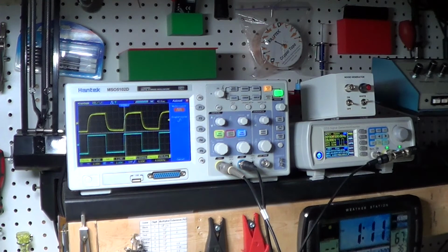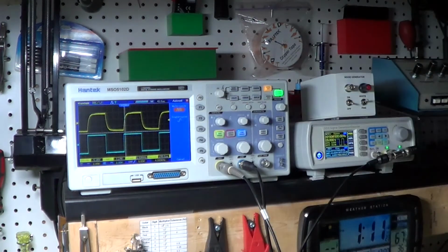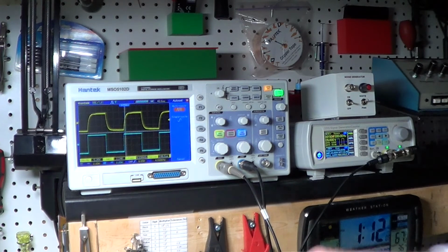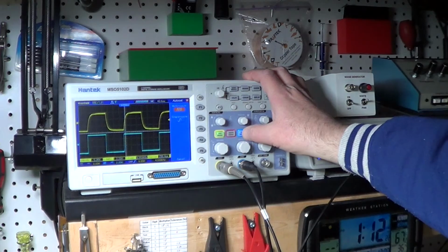We can even measure these numbers to see how fast the filter is to raise the signal from the bottom to the top and how fast it is to put it back down. And these two pieces of information are called the rise time and fall time. We can measure them using the cursors again, but this time we'll do it in the time domain since we are measuring time right now. The rise time is defined to be the time needed for the output of the filter to go from 10% of its maximum value to 90% of its maximum value. So to do that, let's just work on the output itself.